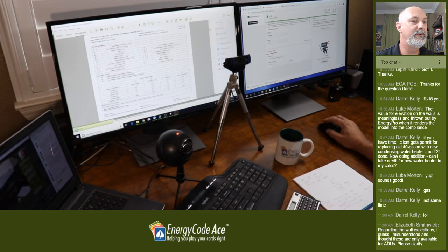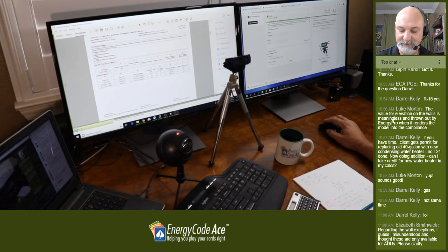Climate zone 12, total conditioned floor area. We could verify that. Area of our addition. We've got 3 zones. We actually have 4, but one of those zones is an unconditioned zone, so it doesn't show up. No natural gas available. Let's look if we got all of our zone areas right. The existing house is 2127. Close enough. Utility room addition. Well, yeah, a little bit different here. We actually have 166. I forgot on my solution to take out that little area for the water heater. And then our bonus room, again, is good.